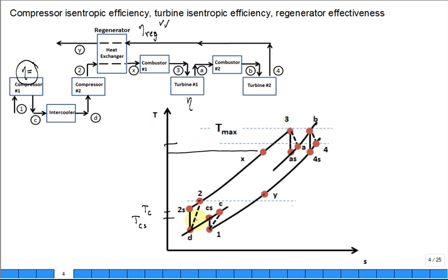So it's the same pressure. This line right here is a line of constant pressure, right? Between state Cs and state C, but the temperature at C is greater. Put the dashed line indicating increased irreversibilities, increased entropy. S, the entropy at state C, is going to be greater than the entropy at state 1. That all makes sense?